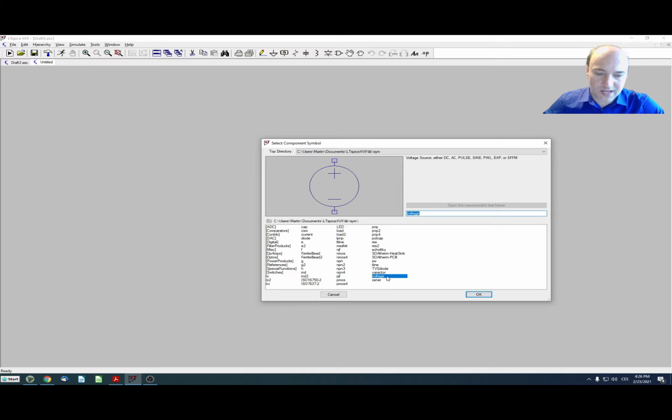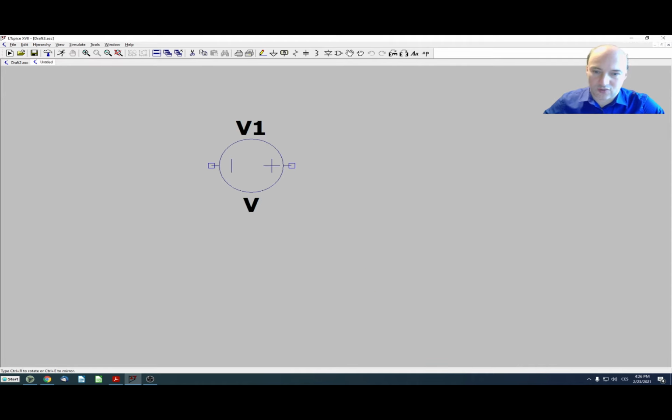So now I'm adding a voltage source like this. I will add it into my circuit, and I will orient it so that I can arrange the three power supplies next to each other. I will first insert only one of them, and I will define its parameters, and then I will just copy the other two remaining sources. So now I have one voltage supply. Let's leave the name as V2.